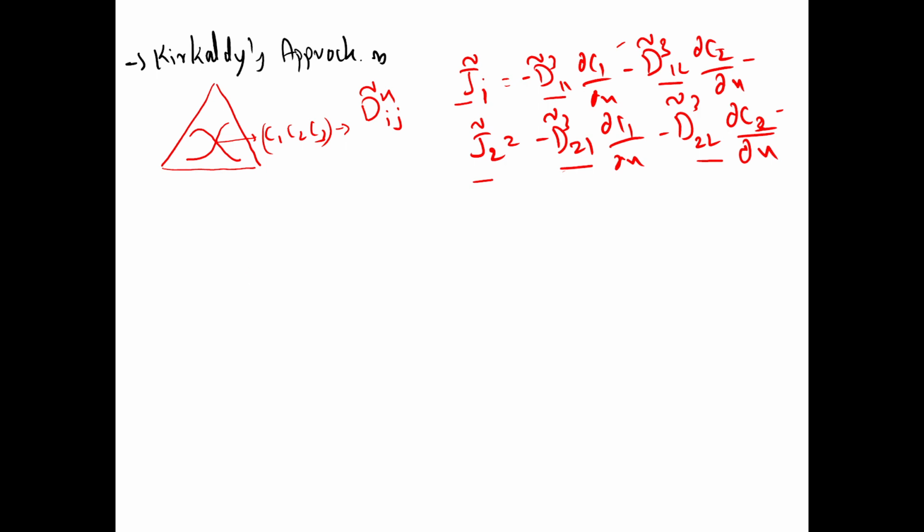These J1 and J2 are calculated from the previous equation that we mentioned in the last slide. So we'll get J1, J2, right? After that, we need to determine the concentration gradient of the first component as well as the second component at this intersecting point. By solving these two equations, you'll get the value of